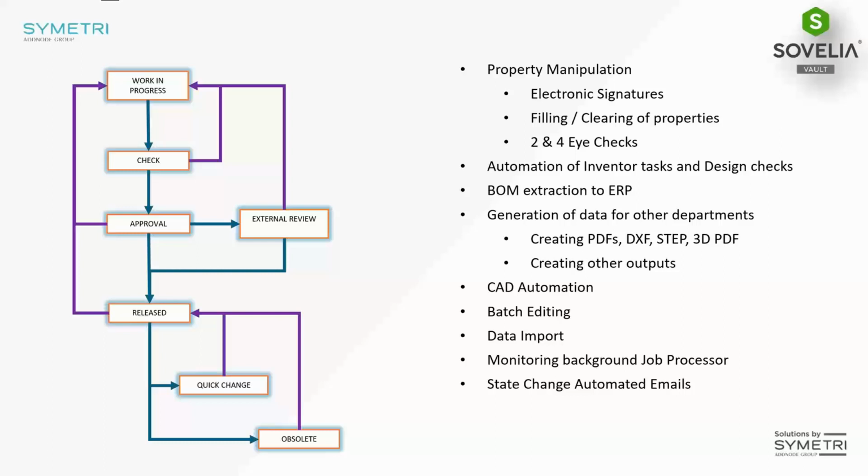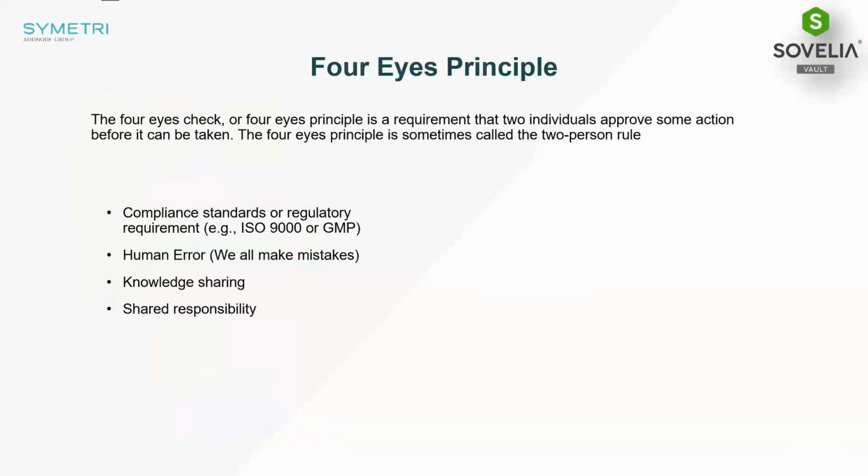So again, we can set up groups within the Vault, and we can email the relevant people in the relevant groups when certain files are changed. And you can set up rules that it goes to this group if the file is in one folder structure or folder set, and it goes to another group if it's in another. Or you can apply these based on categories if you're using Vault categories. There's a lot of options around automating these workflows.